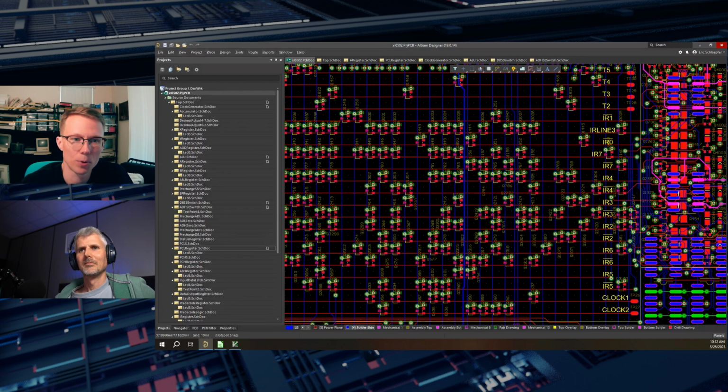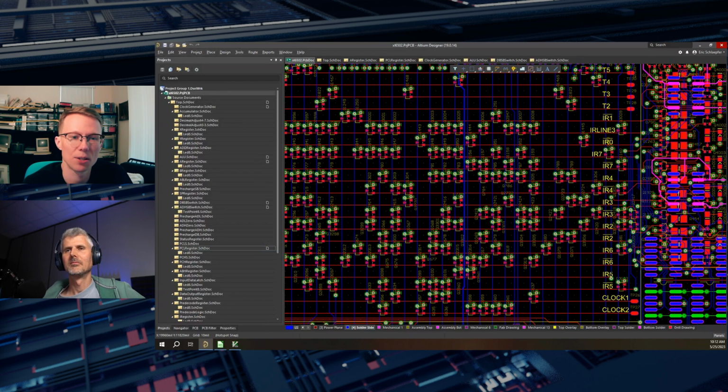What I wound up doing was pulling together a test program that runs a whole bunch of 6502 instructions. And I did it in two stages. The first stage is to verify bus activity. The program runs while there is another separate microcontroller that observes the 6502 bus to make sure that the bus cycles all look correct. And so that's a cycle by cycle verification. It doesn't verify all the inner workings of the chip, but it does verify basic functionality.